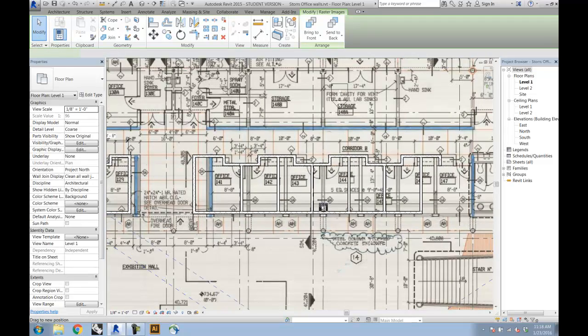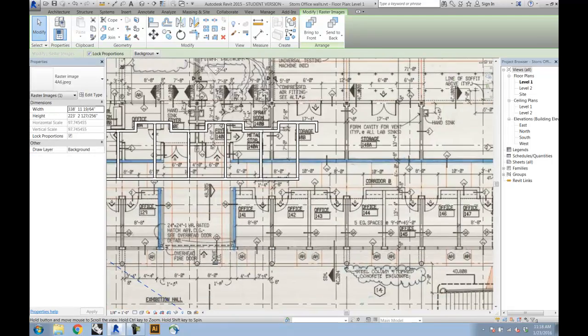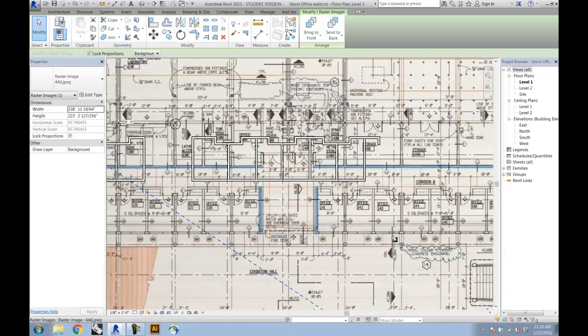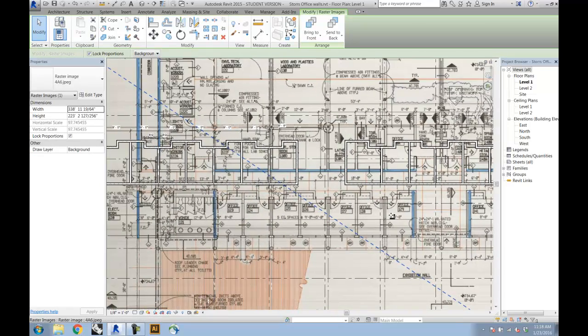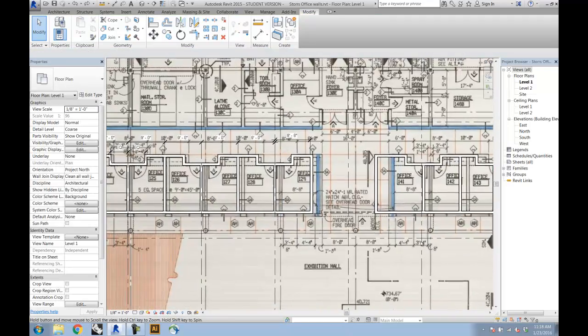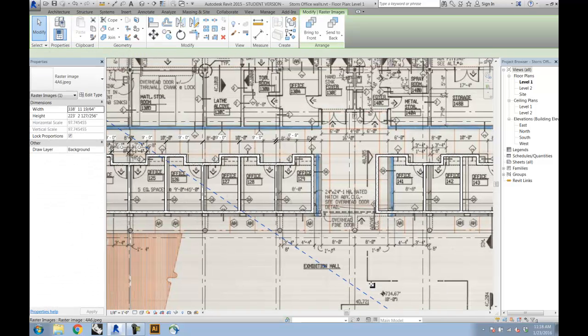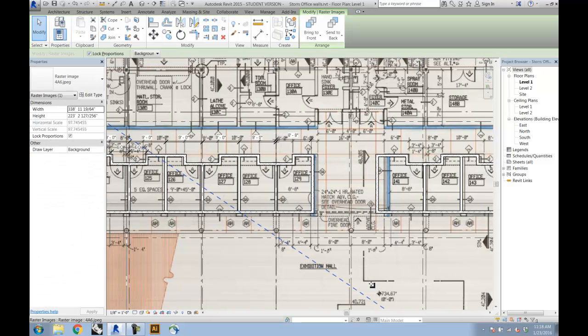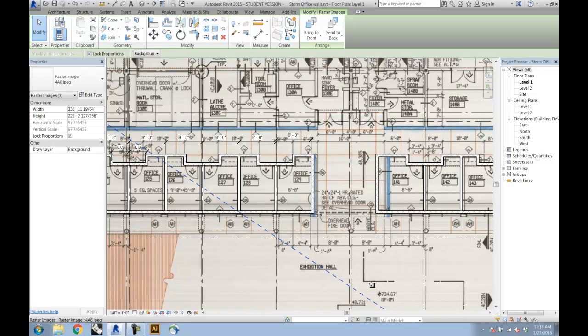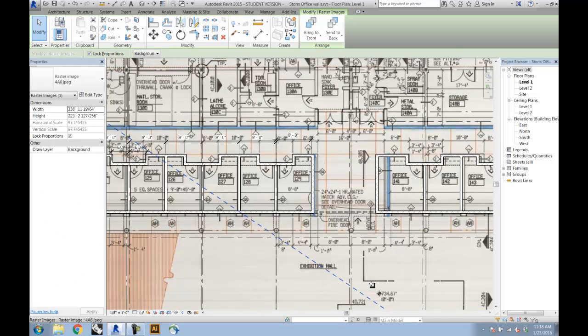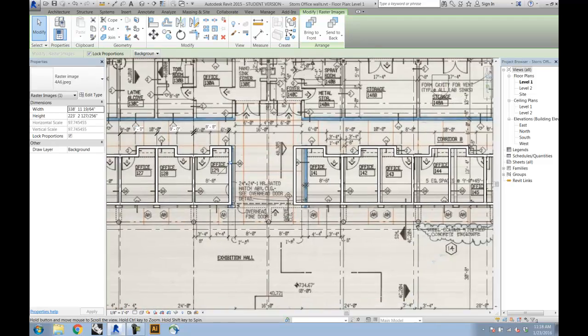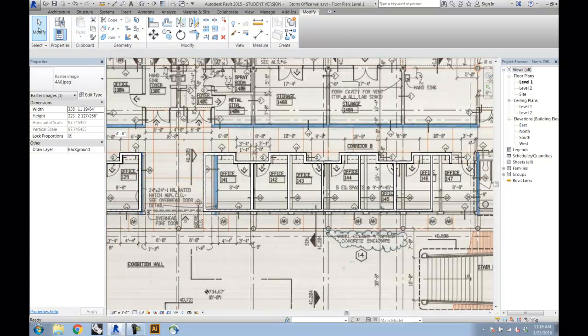Instead of fixing this side, you can see how there I started dragging to select, and it actually dragged the drawing. I'm going to hit undo. If I want to constrain this, well, first thing I might do is just make some adjustments to the location of it now to get it a little bit closer to where it should be. But I can select it and hit the little pin up here in the top row, and that's going to pin it down so that it no longer can move.